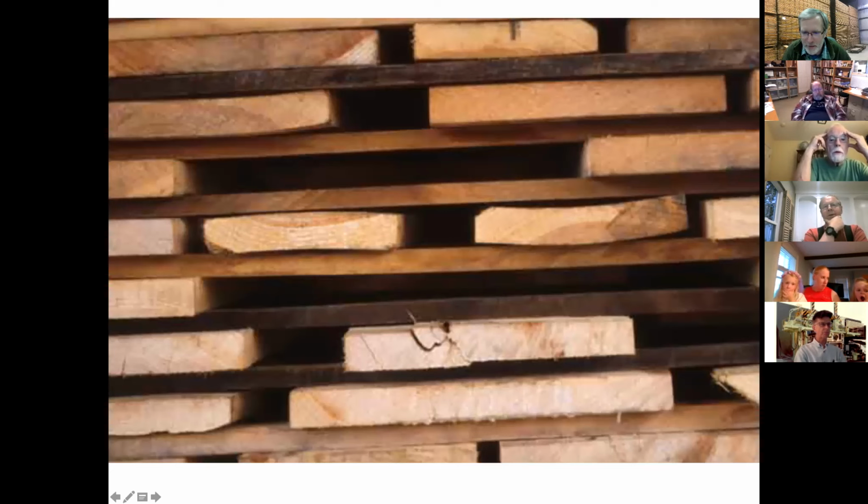But then you'll say, Dr. Bond, something doesn't make sense. These other boards look really flat. Well, you'll notice in the stacking here that there's no pressure holding these boards together as the wood dries. Whereas here, you've got weight distribution through the entire pile holding those boards flat. And these boards are a little bit more quarter sawn, which is why they're more flat. And I apologize, you can't really see the grain there.